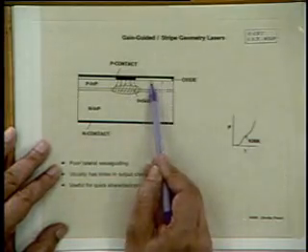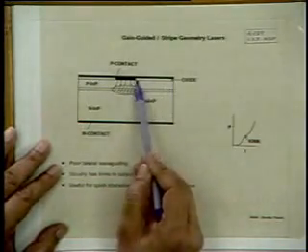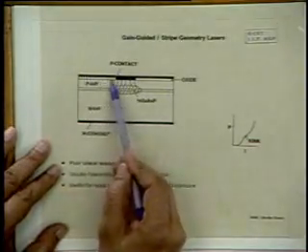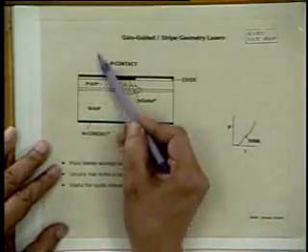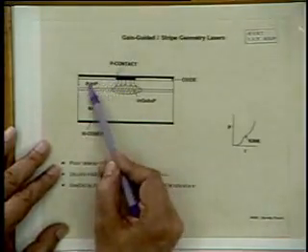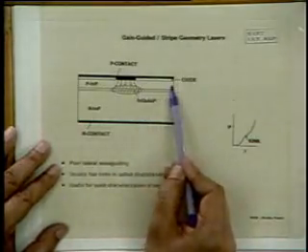Okay, this is called an oxide. You have an oxide, and here you don't have an oxide. Okay, so you metallize, and the metal makes contact only to this region. You can have proton isolated lasers. That means that if you make a mask, you bombard this area with protons. If you bombard it with protons, this area becomes high resistivity.